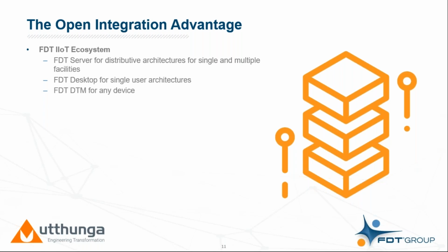And then the other part of the equation is the FDT DTM. So these are essentially the device drivers that the device manufacturer writes in accordance with the standard that describes their device, interacts with their device. It has wizards in it so that they can help you through the configuration or troubleshooting the device. It usually has the manual associated with the device, and other things are all built into that DTM that's supplied by the device manufacturer.